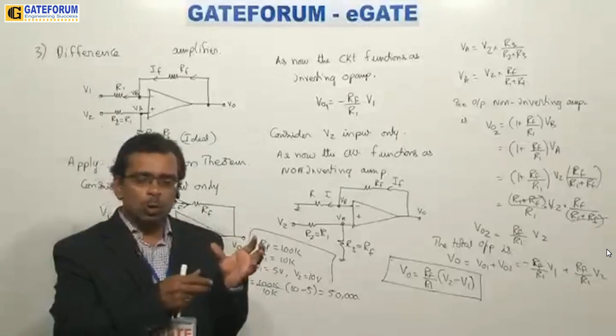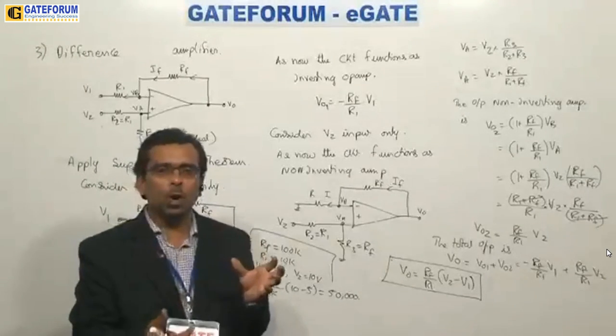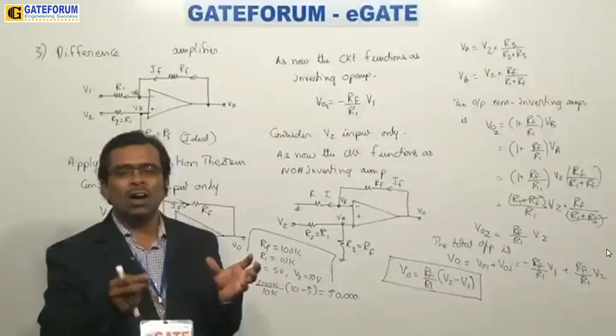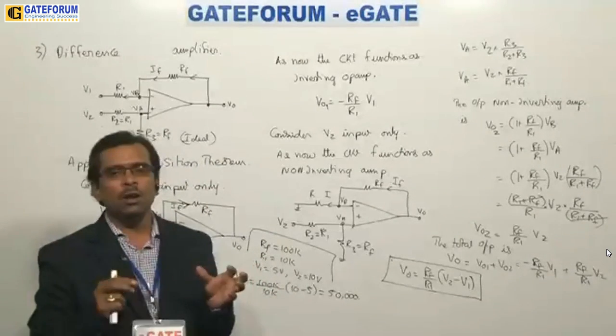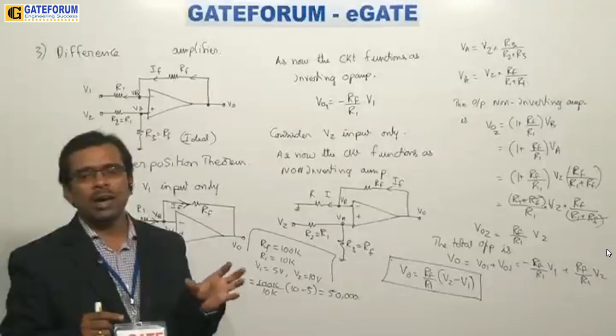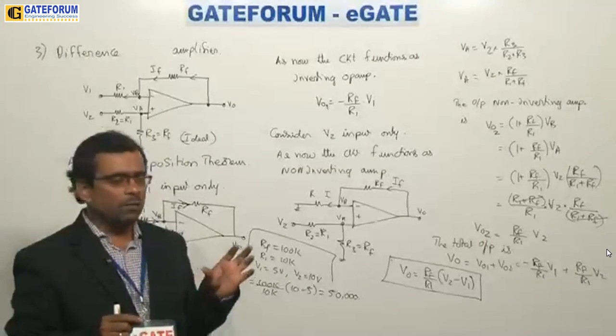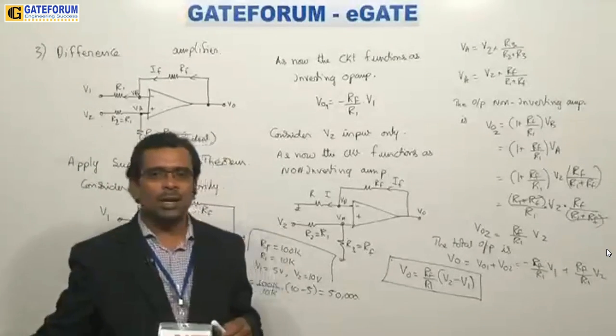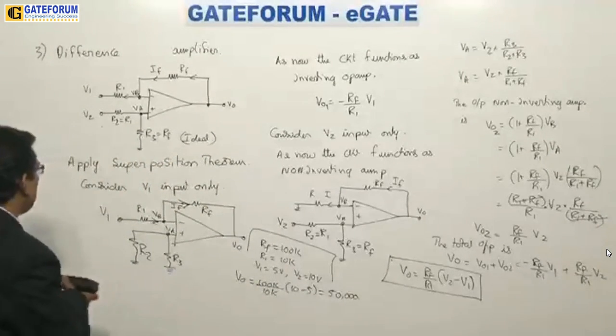They very well know that definitely there will be some errors. That is the reason they have wantedly put one pin called offset. Pin number 5 we have as an offset pin. So definitely you should know about this part. In order to handle this, let us see this configuration.